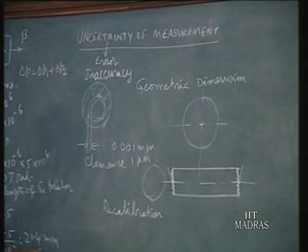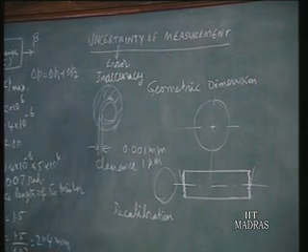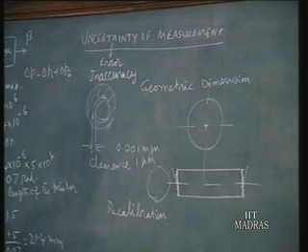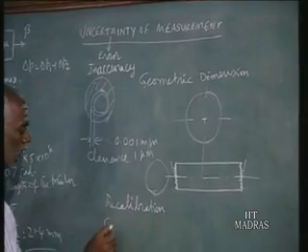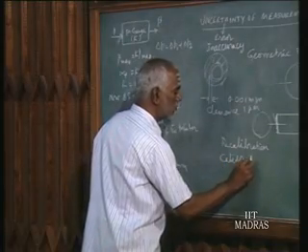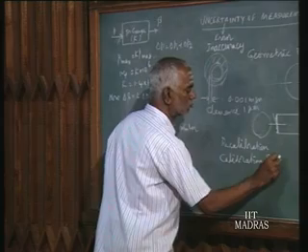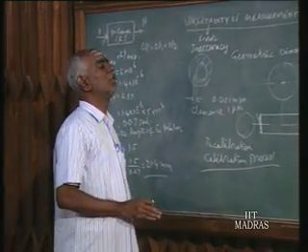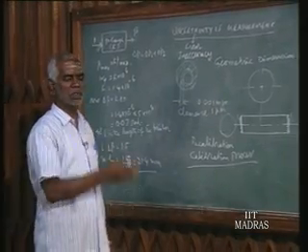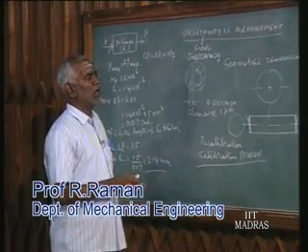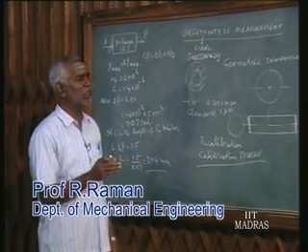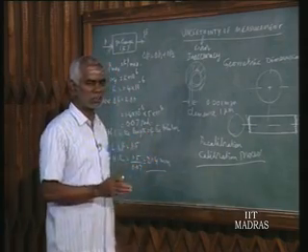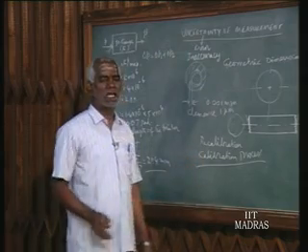Or when we make an instrument for the first time, again the scale of the instrument is to be calibrated. For that purpose, we have the so-called calibration process. In this process, we have to realize the same atmospheric conditions in which the instrument is going to be used. Whatever error we claim for the instrument, say within plus or minus 1%, holds under certain atmospheric conditions. Those conditions are to be realized for the calibration process.